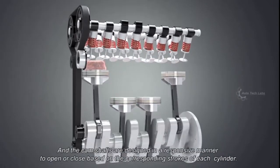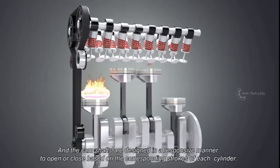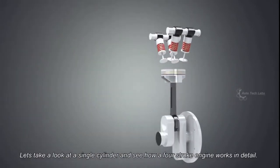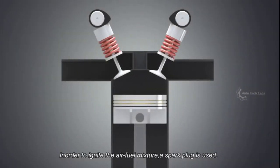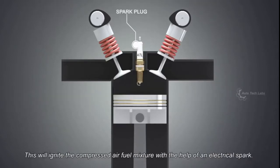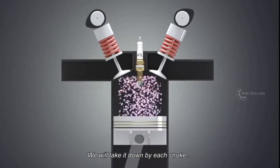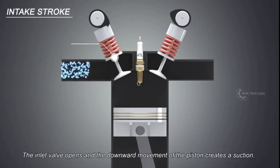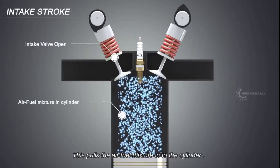And the camshafts are designed in a responsive manner to open or close based on the corresponding strokes of each cylinder. Let's take a look at a single cylinder and see how a 4-stroke engine works in detail. In order to ignite the air-fuel mixture, a spark plug is used. This will ignite the compressed air-fuel mixture with the help of an electrical spark. We will take it down by each stroke. The intake stroke. The inlet valve opens and the downward movement of the piston creates a suction. This pulls the air-fuel mixture into the cylinder.